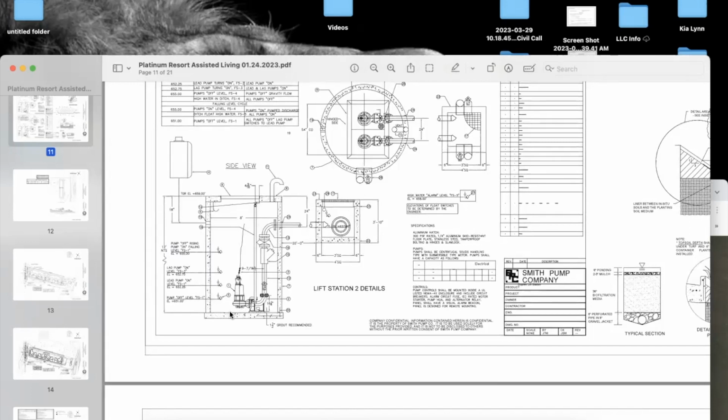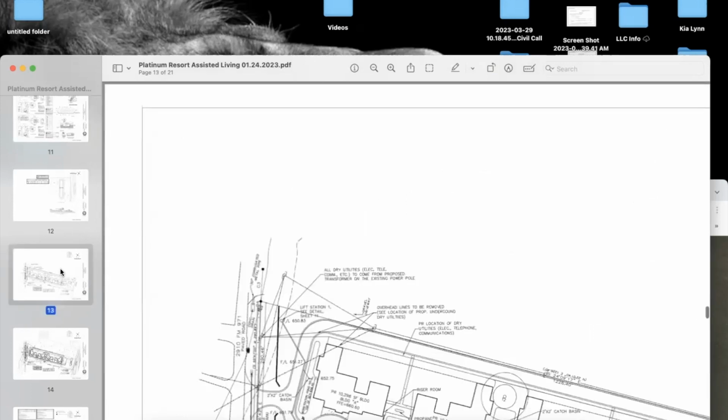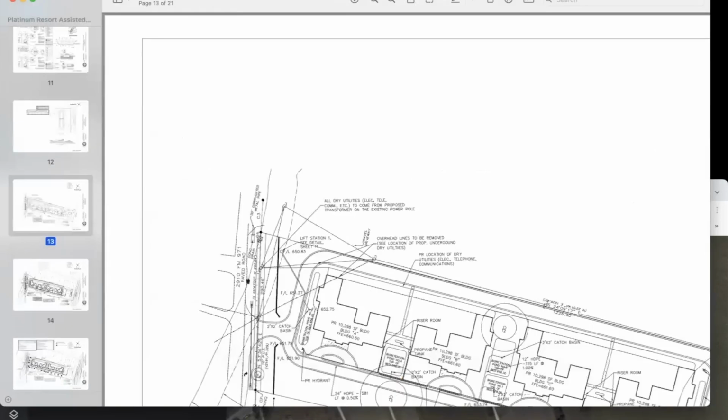And essentially it's almost like a little septic pump tank, right? It fills up enough water, it hits a float, and then it pumps out. So this is an option. For me, she thought it was going to be more cost effective. I think it's going to be more expensive than doing a detention pond. But really, what are my options? I used up a lot of the site.